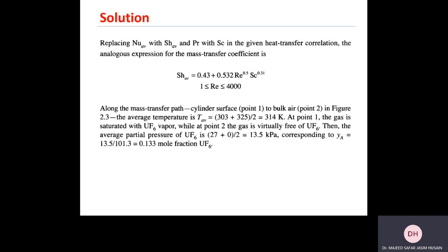The average pressure is 27 plus 0 divided by 2, so it is 13.5 kilopascal. And if you want to change it to mole fraction, you take the 13.5 and divide it by the total pressure, which is 1 atmosphere or 101.3 kilopascal. Then the mole fraction of UF6 is 0.133 at average condition.